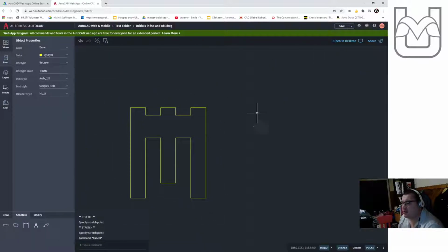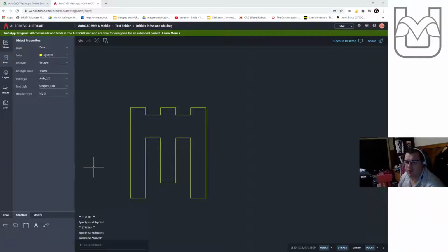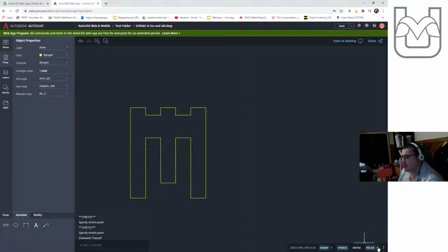Now let's take the edge of this drawing, and we know that oblique draws the Z direction, so into the page at a 45-degree angle. I'm going to check my polar snaps. Yes, they are at 45s. That's all good. I'm just going to gently move my picture out of the way so you can actually see that. There's your 45s right there.